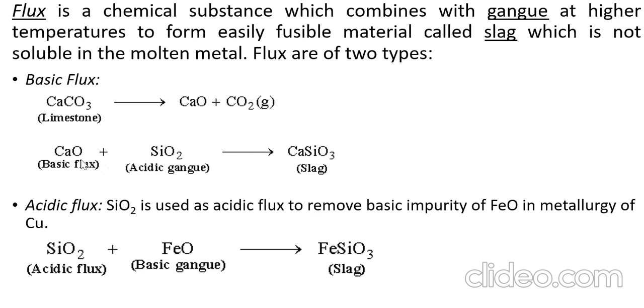Okay. So when you add flux onto the molten iron, it will react with the impurity in the iron to form what we call slag, and this slag is not miscible with the iron, so they can be separated. Usually in the blast furnace, the iron is heavier, it goes down, while the slag is at top. It means the remaining impurity in the iron is removed by adding flux, which forms this compound slag.